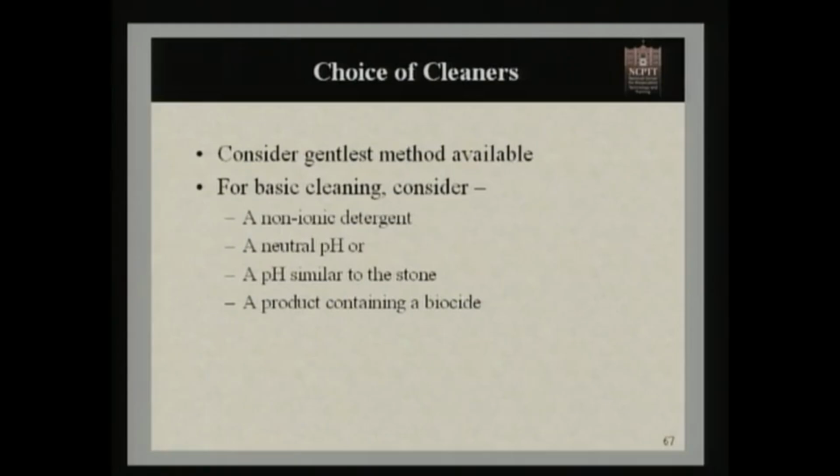And you may also want to look at a product that contains a biocide. Now, one important thing to consider if you are using a biocide is it takes a few days for it to completely take effect. So directly afterwards, your stone is definitely going to look cleaner, but it's going to look a lot cleaner 4 or 5 days down the road as that biocide takes effect and kills the biological growth that's contained on that stone.